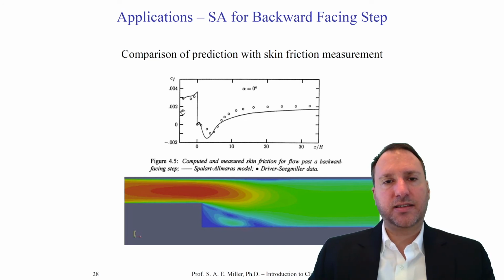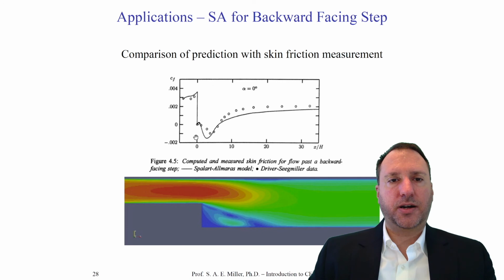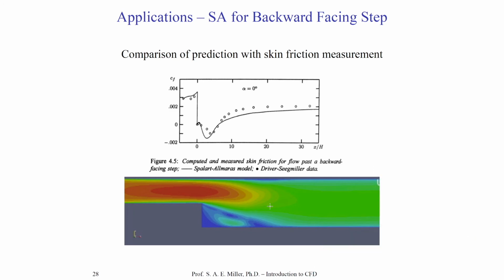You can see this in the skin friction plot here. Here, of course, it's 0, which is where my cursor is now. There's where the skin friction takes a drop because of this step, and then at the wall, which is down here at the base of the wall, it'll have a large drop, and it'll come up again and be reattached at about 10, which is about where my cursor is here. So we can interpret both experimentally and with CFD what's happening exactly in this particular case.